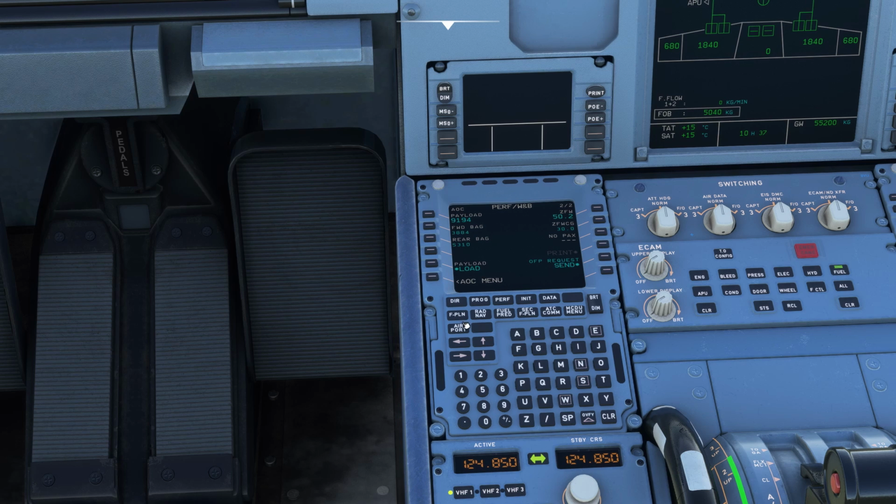All we're going to do then is click init because we're done with the perf, weight and balance. So click init, and then we're going to enter some information about the flight we're taking. So first of all is company route. This will be boxed like this, but I had a mess about with it before, so it's left clear in there. So I'm just going to enter something in there. There are no company routes at the moment. I don't know if that's something they're bringing in later on. So you can pretty much enter anything in there and it won't matter. So all I'm going to do is EGCC1 because we're looking to fly to Manchester today.